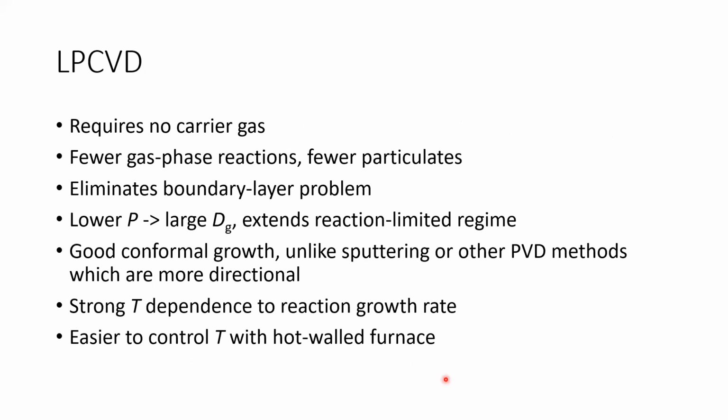So for LPCVD, low pressure CVD, there's no carrier gas. We use low pressure. There's no nitrogen there. We have no carrier gas. And because of the low pressure, low collision, there are fewer gas phase reactions, fewer particle contamination.